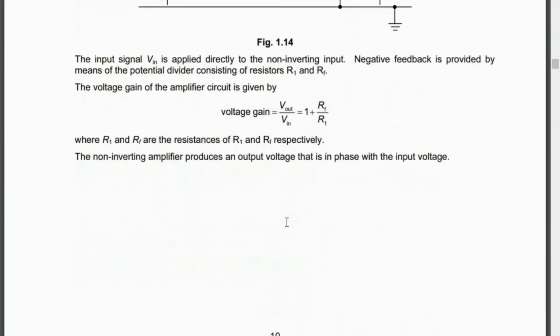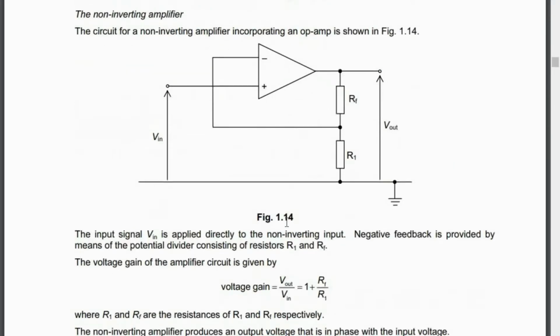Guys? Alright, now let's move on to the next thing, which is the non-inverting amplifier. Alright, so non-inverting amplifier. How do we know that this is non-inverting? Really easy. Look here, the inverting input is earth. Okay? And the non-inverting input is your input. Okay? Very simple. So in this inverting, look, it's earth across R1. It will have a value, not exactly zero. It will have a value, but it's connected to the earth. While the non-inverting is not at all connected. So this is the easiest way to determine this as a non-inverting input.